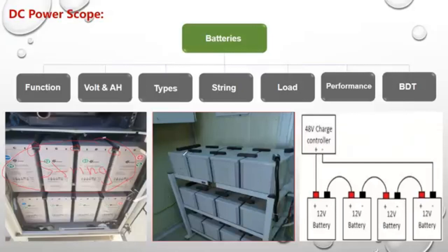Now, this is another type, which is 2 volts. If you count them, you'll find 24 batteries. So 1, 2, 3, 4, 5, 6, 7, 8, and then 8 times 3 of these, so 8, 8, 8. That's 24 batteries in total. They're all connected to give me 48 volt DC, and this is used in the telecom devices. And all of this together is just one string.